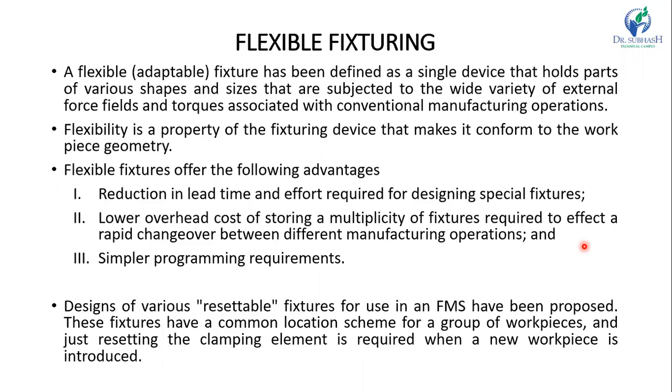So designs of various resettable fixtures for use in an FMS have been proposed. So these fixtures have a common location scheme for a group of workpieces, and just resetting the clamping element is required when the new workpiece is introduced.